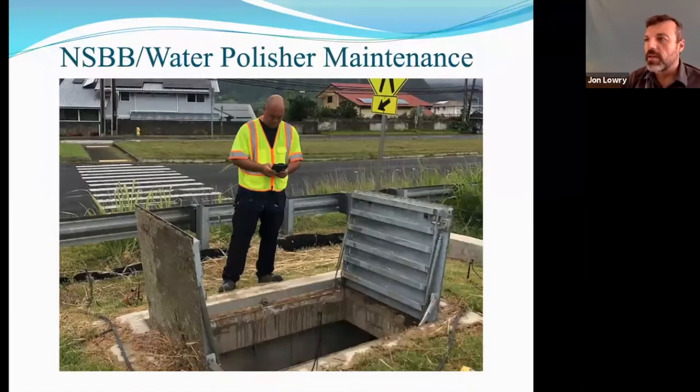And then here's just another view of one of the water polishers. We've tried on our more recent designs to use these access hatches rather than manholes in areas that are located behind guardrails, for easier maintenance. But again, the contractor, we're going to ask you to be responsible for this maintenance for the first 9 to 12 months. And that's going to require, for the baffle boxes and water polishers in particular, for you to have a vac truck.